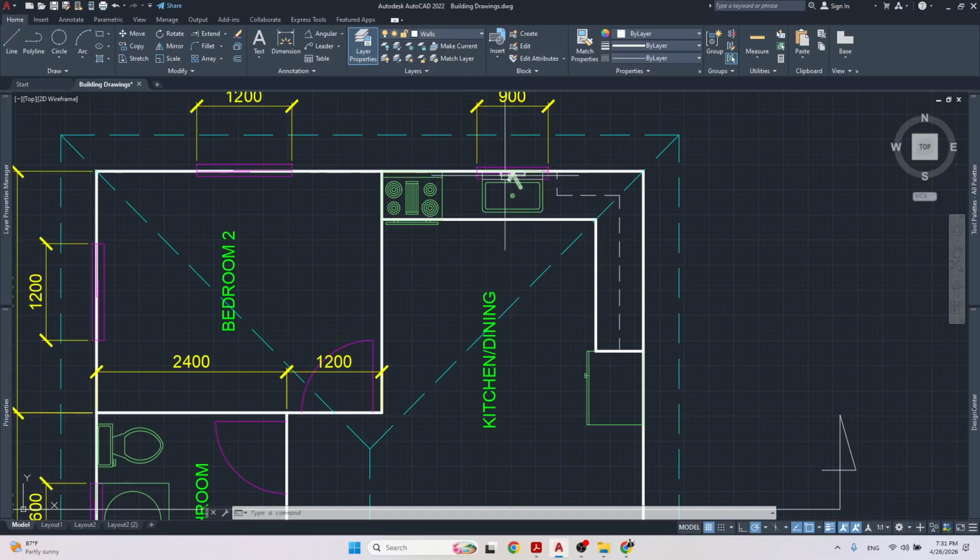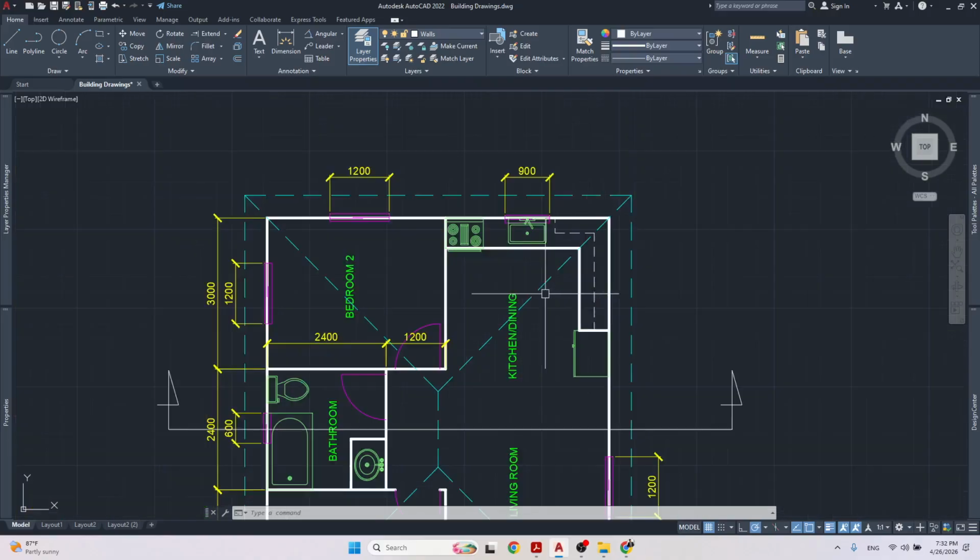But kitchen, because of the counter, which is also 3 feet off the floor, that means the window has to start a little higher. So the window would start 4 feet off the floor. So that means this window is going to be 3 feet wide by 3 feet high instead of 4 feet high as it would probably normally be. Alright, so